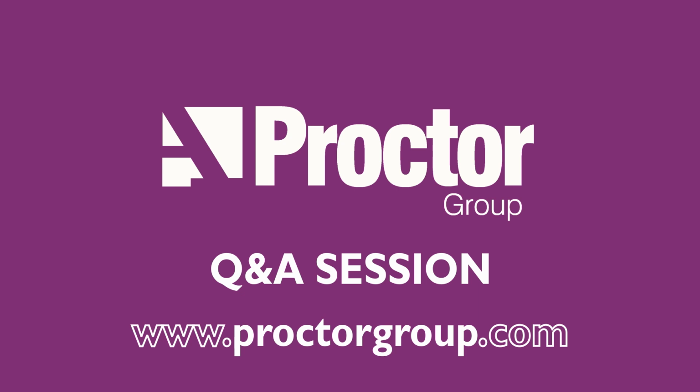Okay, good, thanks. Just another quick one from Michael as a follow-up to his last question. Is WUFI analysis beneficial in modelling the effects of damaged or incorrect vapour control or building services / ventilation? Yes, it's always a difficult one to look at sort of penetrations and damage of incorrect vapour control layer. The way of using WUFI analysis is to actually look at the dimensions of how the building changes when you actually include a vapour control layer or remove a vapour control layer. That's one of the parameters that we look at right at the initial stages of design.